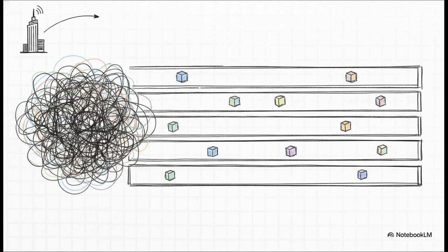Each lane or subcarrier is independently modulated, and because they're orthogonal, they don't interfere with one another at all. This provides an incredibly robust defense against multipath fading, which is just what happens when signals bounce off buildings and arrive at your phone at slightly different times.